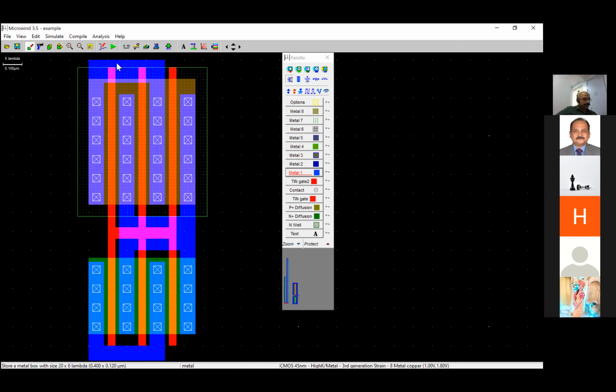Shall I proceed? Yes, sir. Okay. Now you take the VDD supply, left click on the VDD, and very carefully on the corner of the N well, you can left click again. On the corner of the N well, the green one. So it is placed on the N well now. So now your N well will be reverse biased to the VDD.